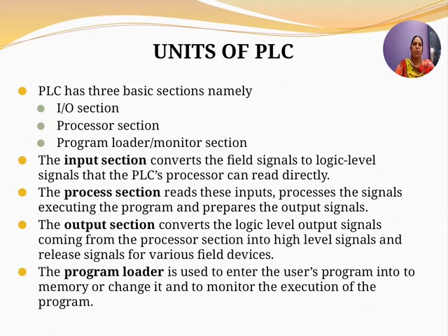So the input section, what does it do? It converts the field signals to the logical level signals that the PLC's processor can read directly. Then the second section is your processor section, which reads these inputs from the input section, processes the signals, executes the program and prepares the output signals.